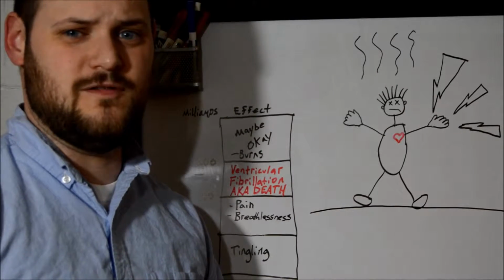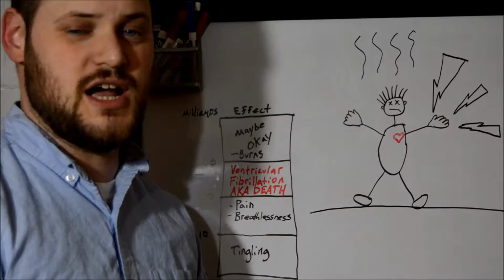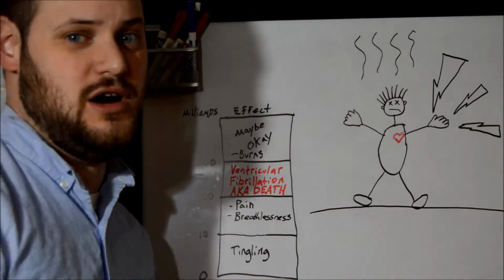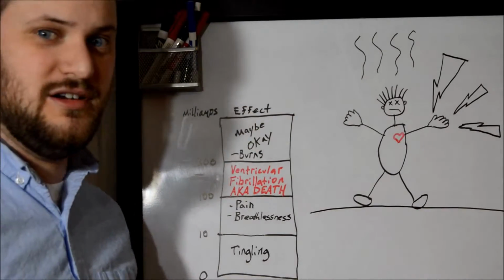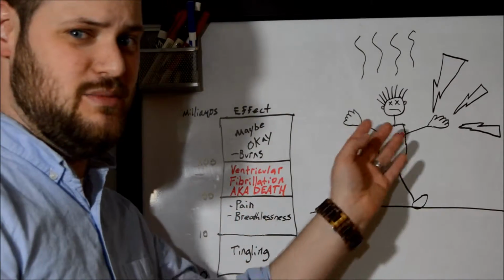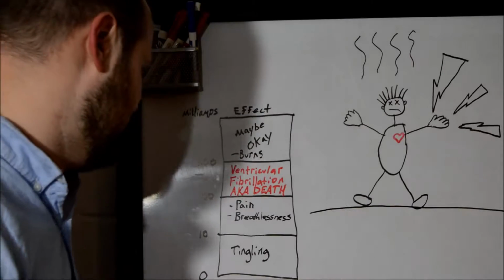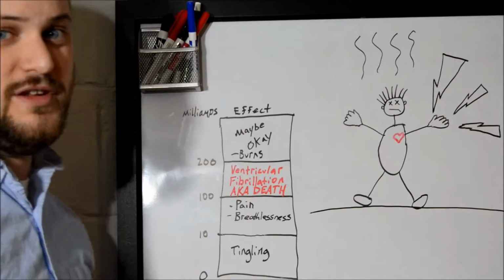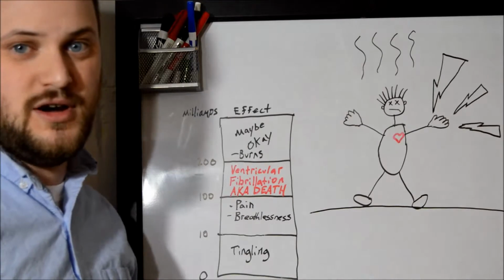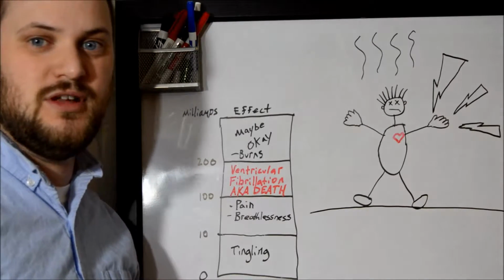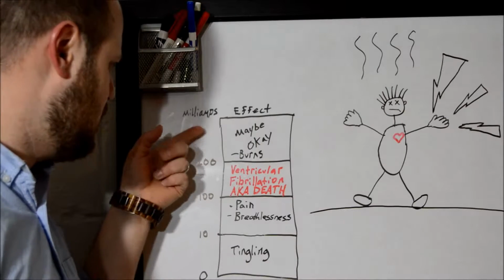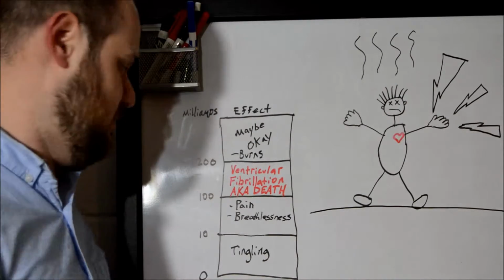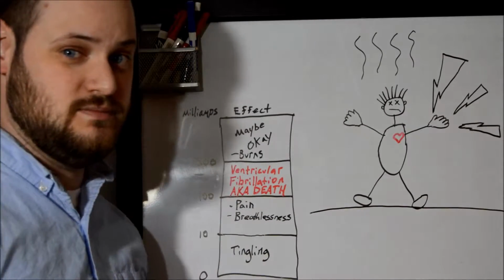Okay, so when I talk about fatal currents or currents that will shock you, what am I talking about? What kind of magnitude are we talking about? Well, I've made a little chart here, and sorry, my handwriting is maybe worse than my drawing abilities, but we're talking in the order of milliamps. Yeah, if you think about it, what are the circuit breakers in your house? 15, 20 amps are typical. Way larger, orders of magnitude larger than the milliamps we're talking about here that can severely injure or kill you.